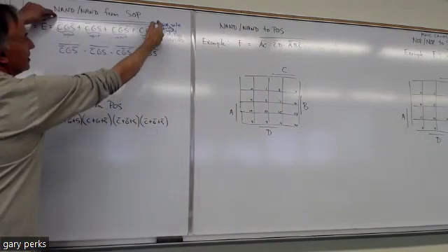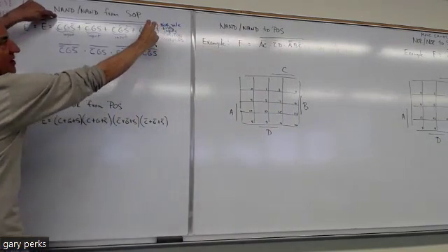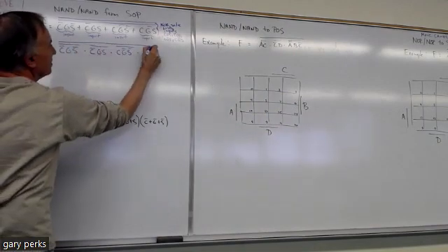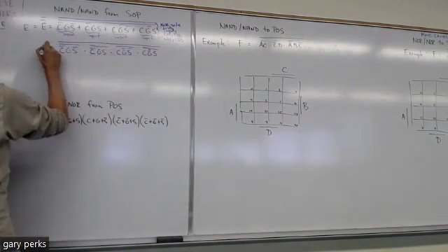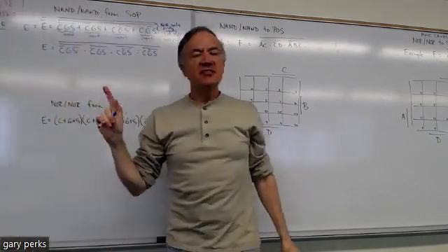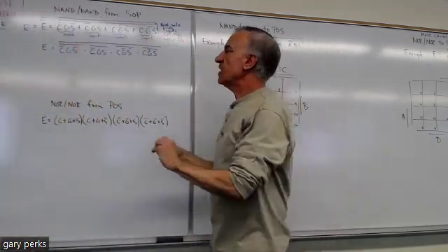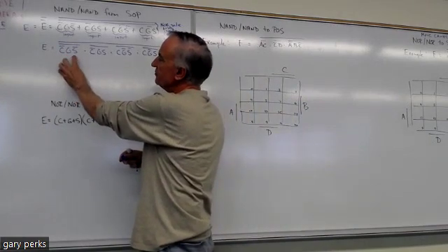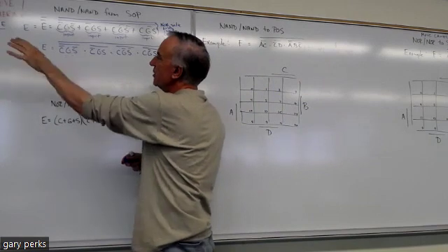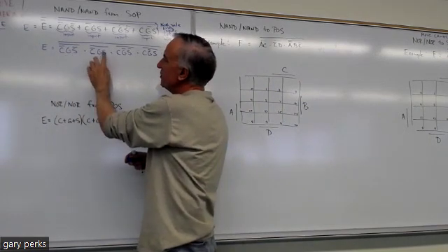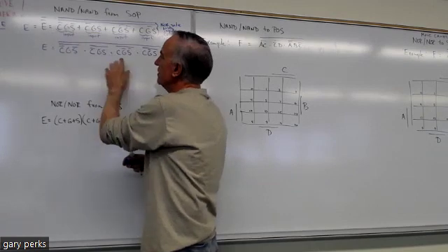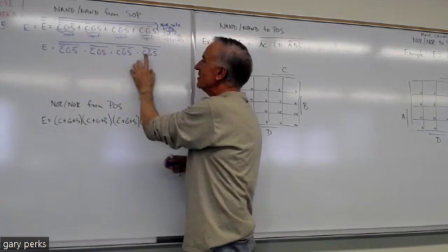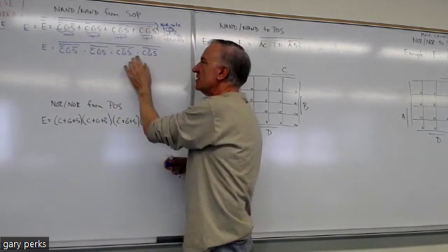And then remember, this top bar wasn't part of this transformation, so that's still there. So after we double NOT both sides and then do De Morgan's once, look what we have. We have this input, this input, this input, all ANDed together, the whole thing inverted. This input, this input, this input, all ANDed together, the whole thing inverted. And the same for the remaining two terms.